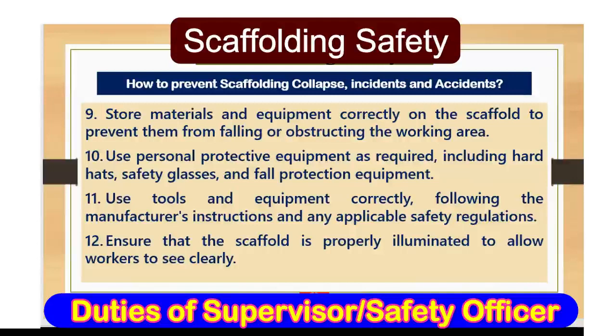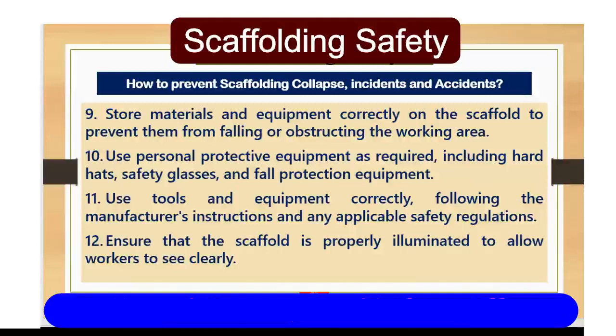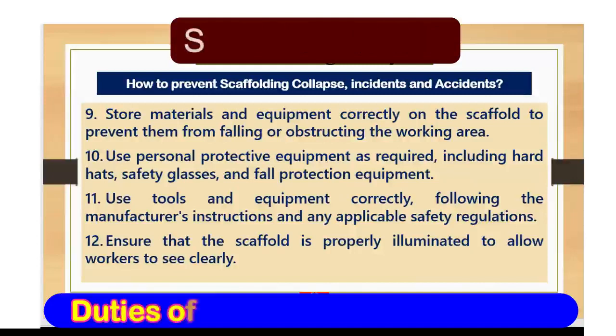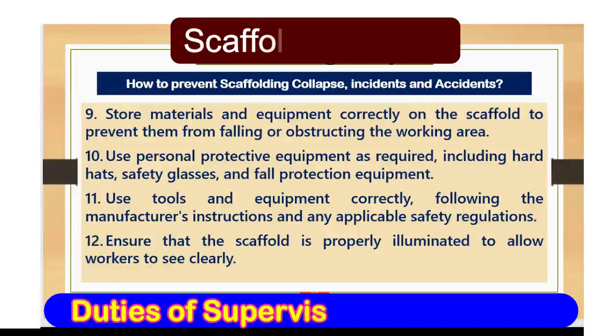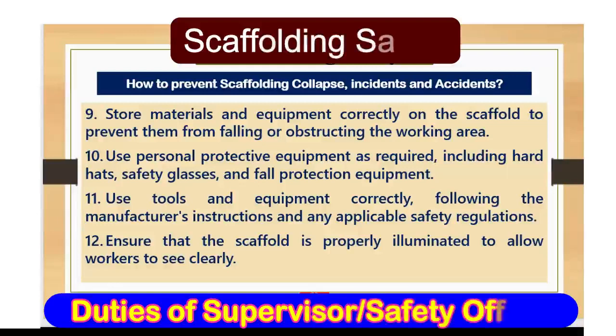Number 10, use personal protective equipment as required, including hard hats, safety glasses, and fall protection equipment. Number 11, use tools and equipment correctly following the manufacturer's instructions and any applicable safety regulations. Number 12, ensure that the scaffold is properly illuminated to allow workers to see clearly.